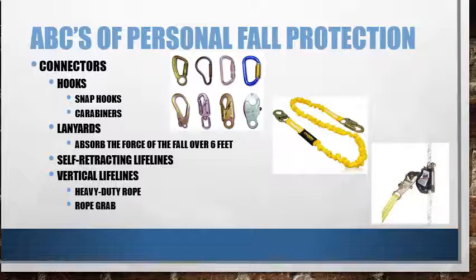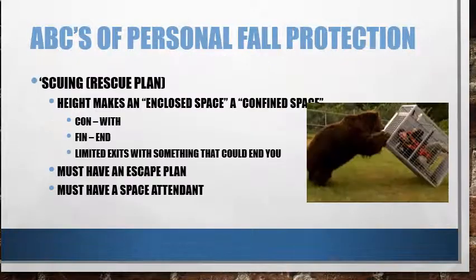There are self-retracting lifelines, which will slowly lower you down, and there are vertical lifelines, which would involve a heavy-duty rope attached to the top of a building, and then a rope grab, which you adjust as you move up and down, keeping it tight so that you're being protected from falling.